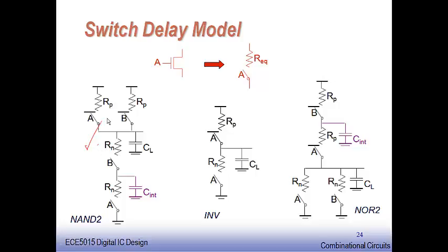Now we are assuming a 2-input NAND gate here. In this 2-input NAND gate, naturally one device B and another device A are connected in series, and you have the PMOS devices, that is the dual network, in parallel. Now with this structure, what I am showing you here is, for each device you depict the resistance of the device as Rn and another Rn here, with a switch which is controlled by the logic state you have. Similarly here Rp in series with the switch. So this will be connected when you have A bar true, that means when you give a logic low. Similarly B bar will be true when you have a 0 given here.